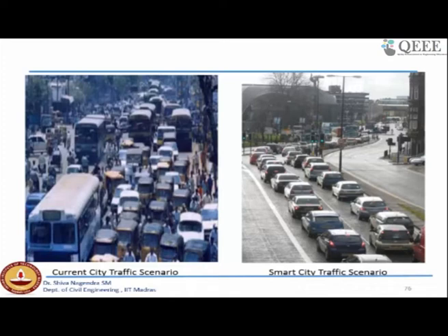Now you have a measured concentration or a model concentration, you have a standard, and you know what percentage is to be reduced. Assume there is 200 microgram per meter cube contributed by this vehicle under the worst case scenario. Now the standard says 100 microgram per meter cube. To reduce it immediately to 100 microgram per meter cube, you have to go for your tactical approach.